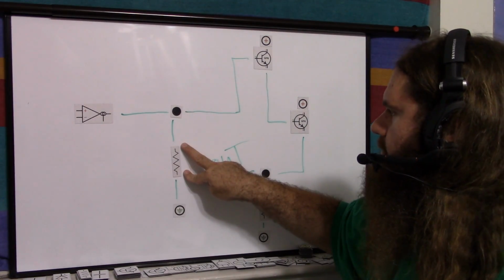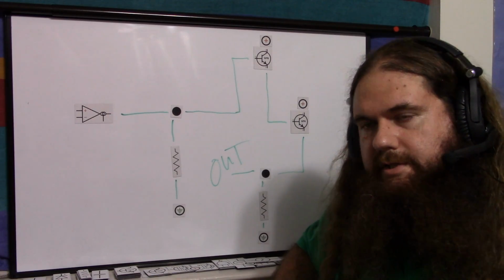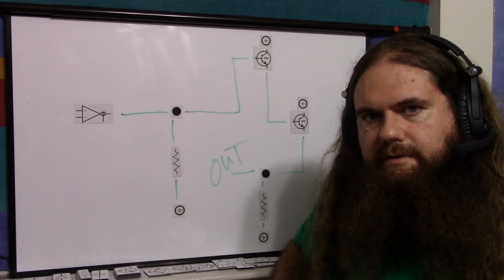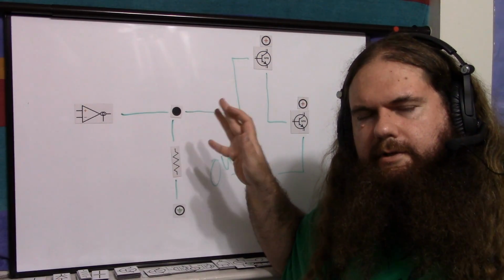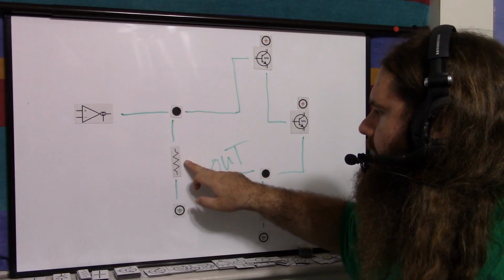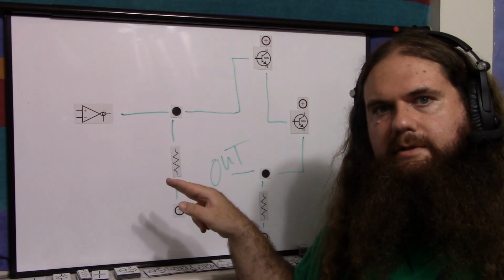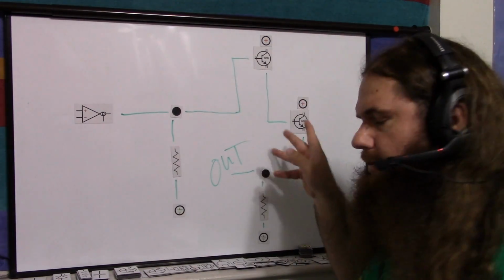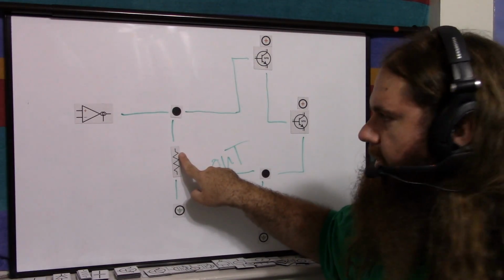So this resistor with these bases will have a roughly constant effective resistance, because your base to emitter is going to have about a constant voltage drop and whatnot. So you don't really think of the bases of the transistors as having a varying impedance. It's there, but it's the same. And this is a constant resistor, this is a constant resistor. So everything is either constant or effectively constant. So your impedance really isn't changing. Even though there's four of them interacting, it's really not changing. So you end up with a nice stable signal because the impedance is not changing.